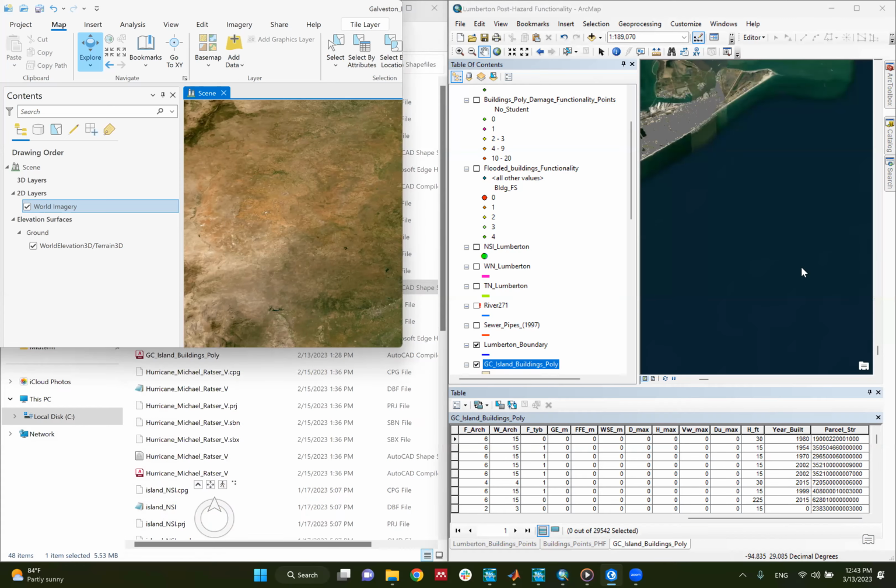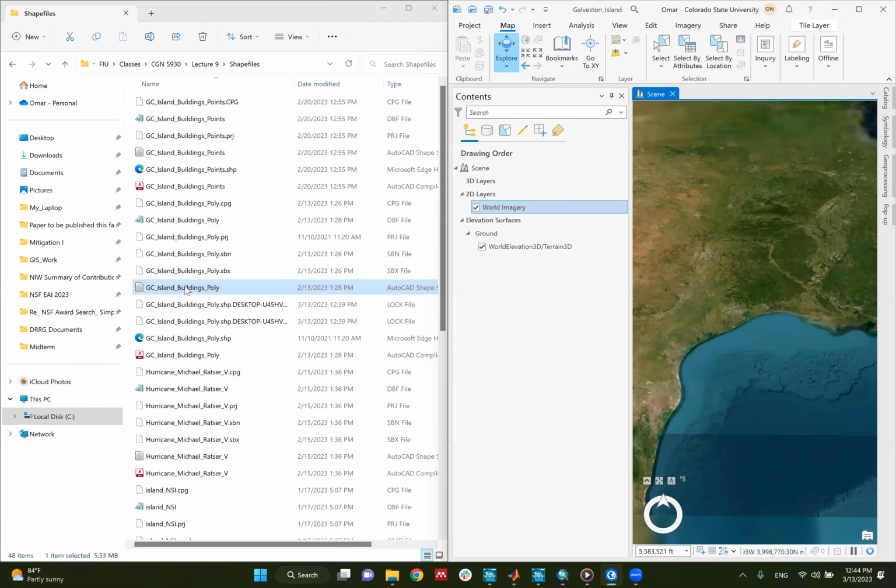That's what I do. I make my screen like this and I drag the shapefile, this file. Actually, I told you, when we have data about the buildings, you will have a bunch of folders. One of them is .spn, .brg, .project. So there's one that is .shp, shape. This one is the one that you can drag, not the other ones. Okay, so I drag the .shp, this one, and I can drop it here.